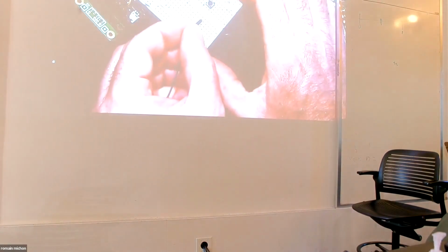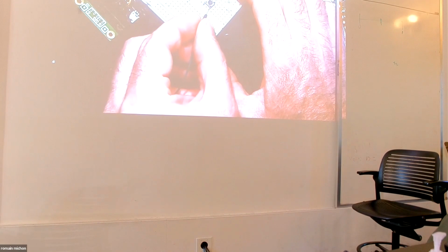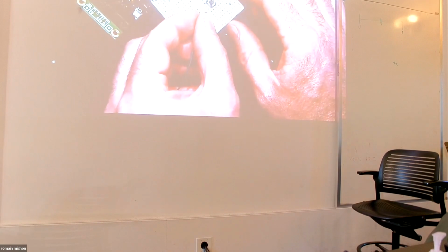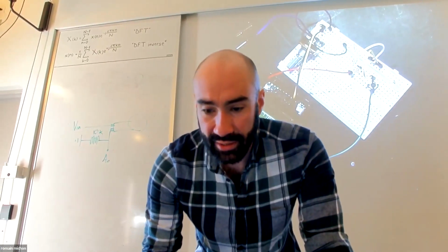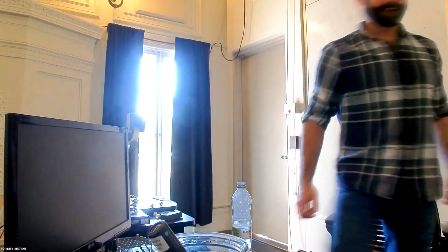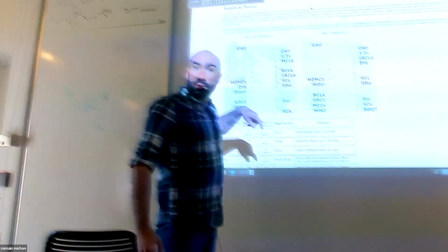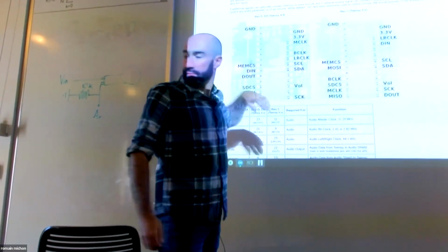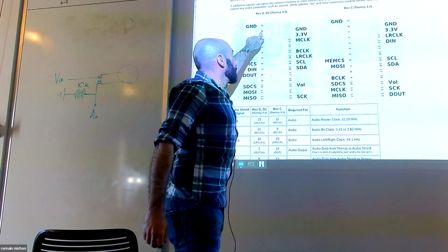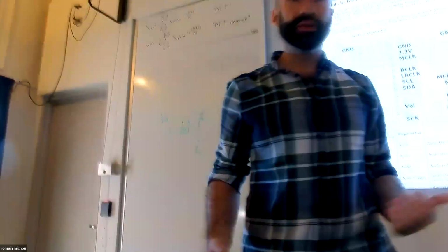And then I'm going to bring the other side of this pin, which is now connected to the ground, to a digital input. So for digital inputs, it's the same as for analog inputs. I need to check which pin is available. On this side, all the pins are digital inputs. So I'm just going to connect to 0, because 0 is available.